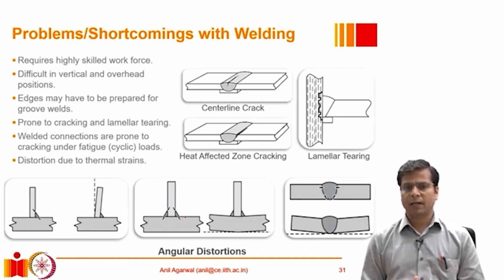Also, very regular, very detailed inspections are required after the welding process, because there is a very high likelihood of introducing any kind of impurity or any kind of distress point in a weld, and that has to be investigated and inspected rigorously after every weld.